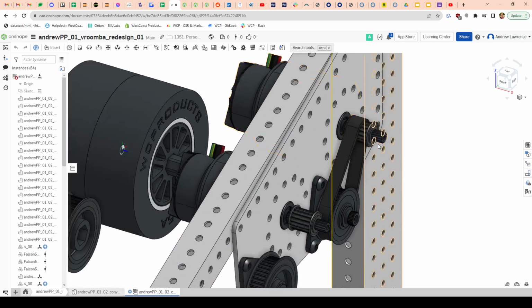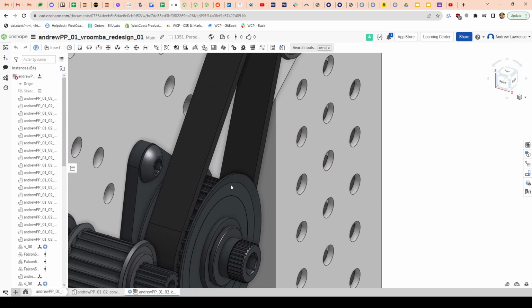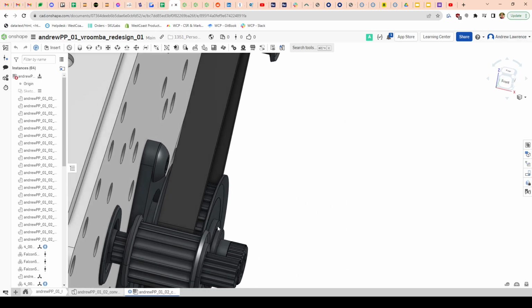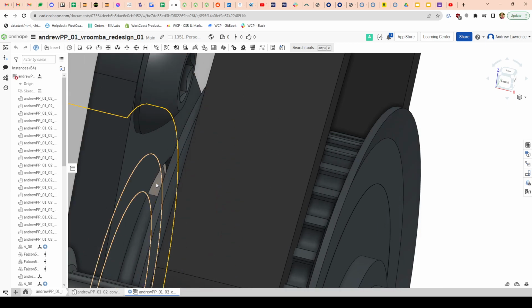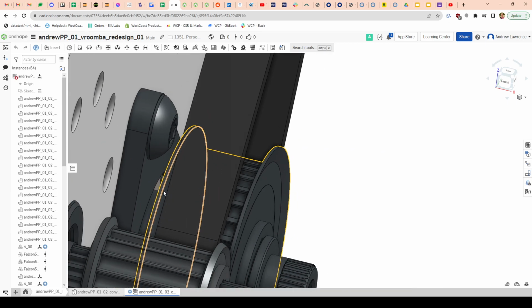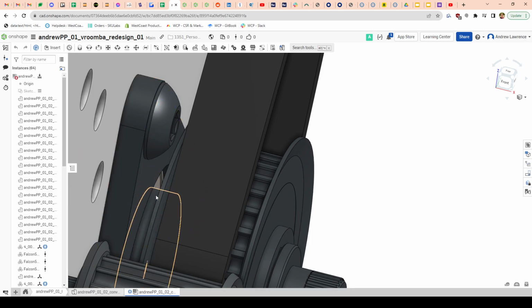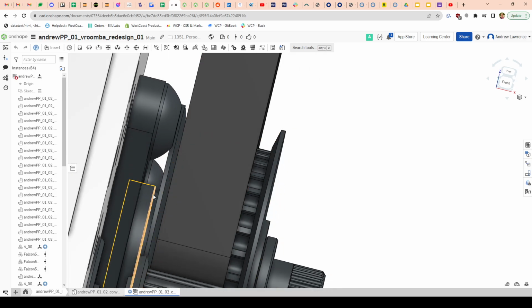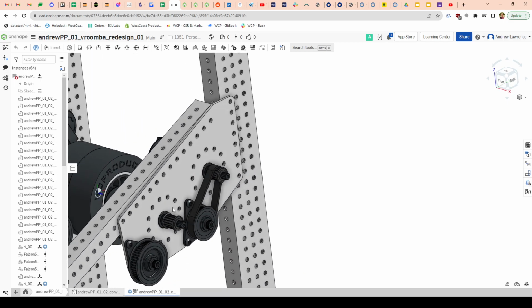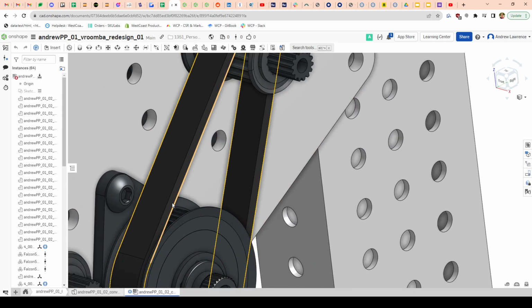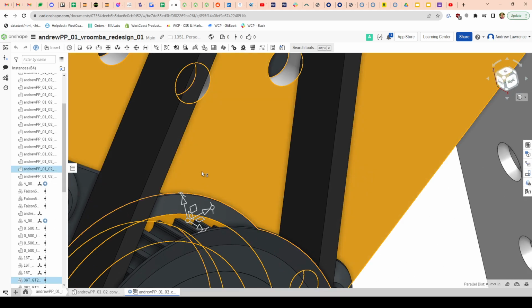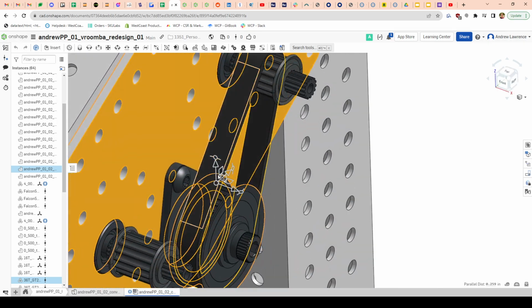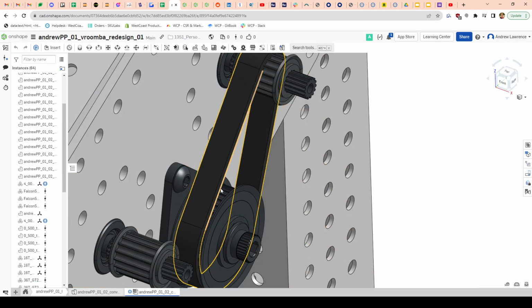In the assembly, I had the pulleys placed before I even had the shafts. Because ultimately, it's barely seen there, you've got a bearing, right? And then I had the cover over it. You have a spacer, and the pulley connects to the spacer. So I don't actually need to have the shaft in there. What I would do is measure how far the inside face of the pulley is from this face of the plate. We got 0.259 inches.